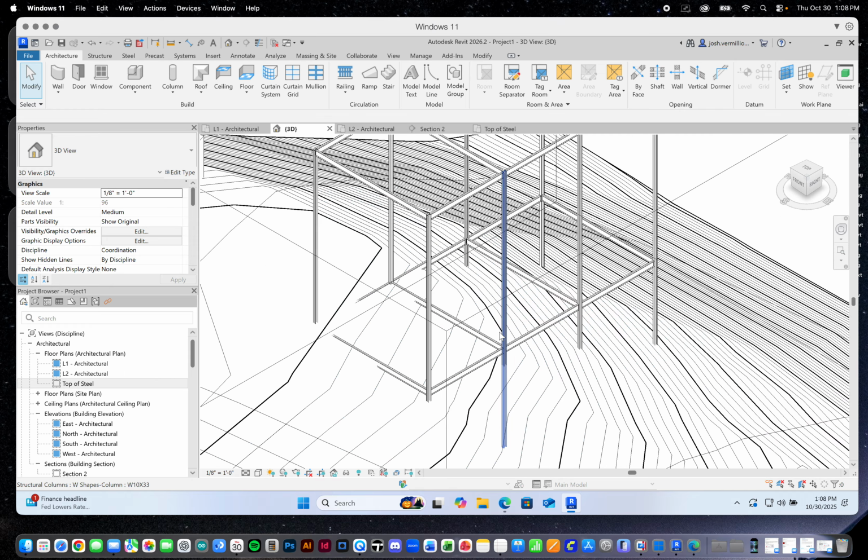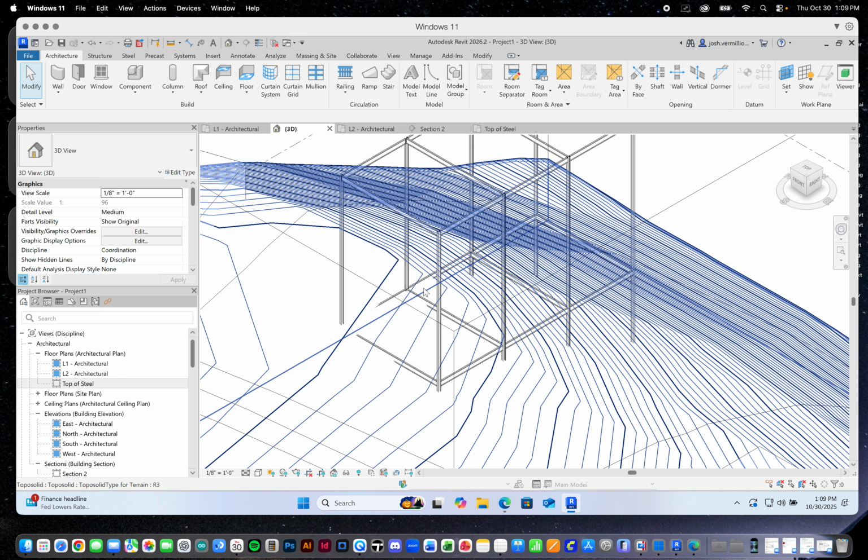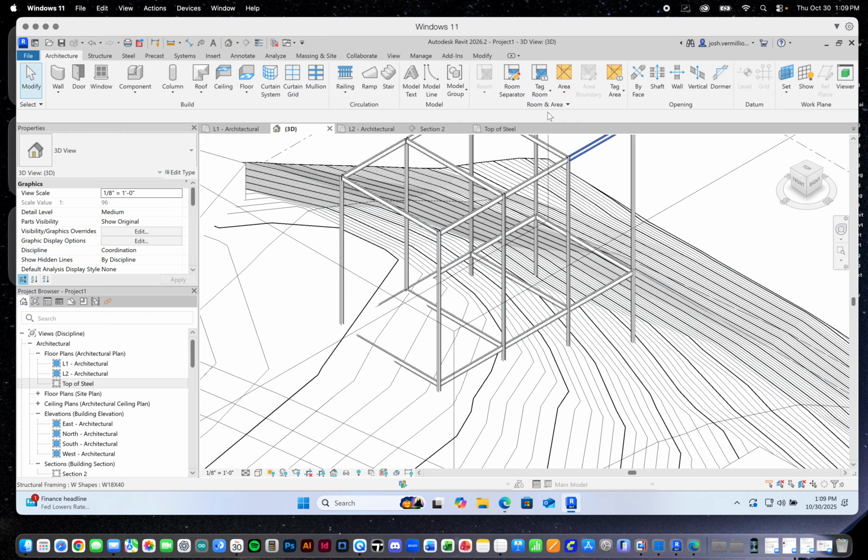All right. Now, last but not least, let's make a second floor. And I'm just going to make one bay of the second floor. I'm just going to make a little mezzanine office above the entrance along the south, the first bay. We have 3 bays running south to north. That first, most south bay, I'm just going to fill in with some columns and some beams at the second floor level, so that later on I can put a little office and staff area up there. But it still wouldn't interfere with this big, tall vista view that we're capturing with our big picture window here on the north end.